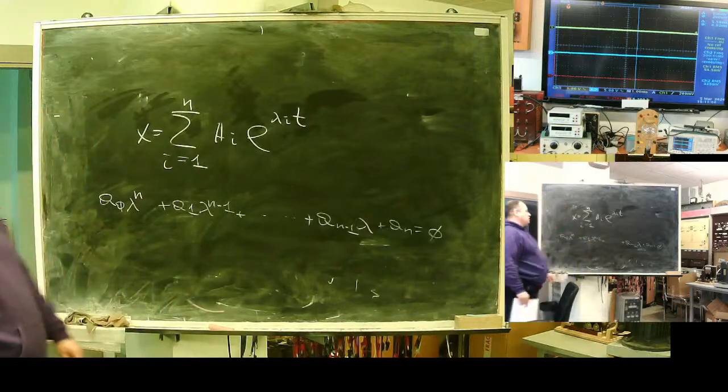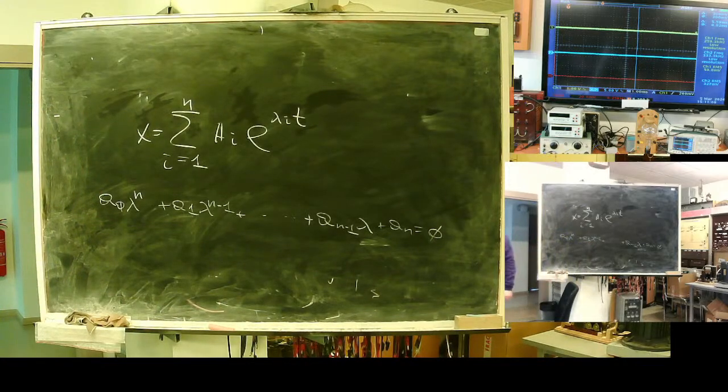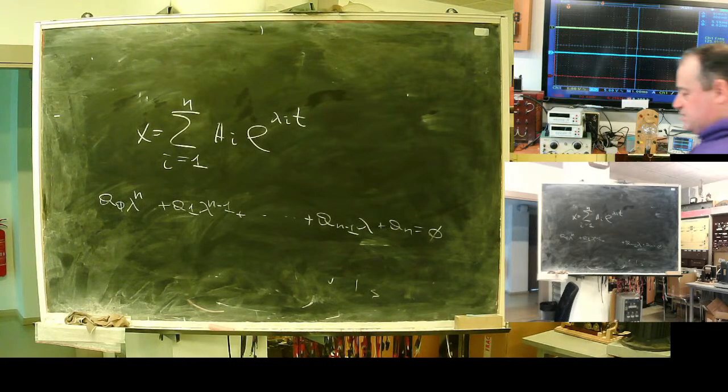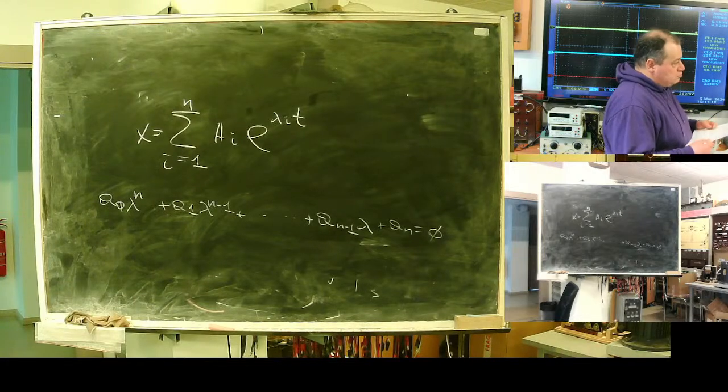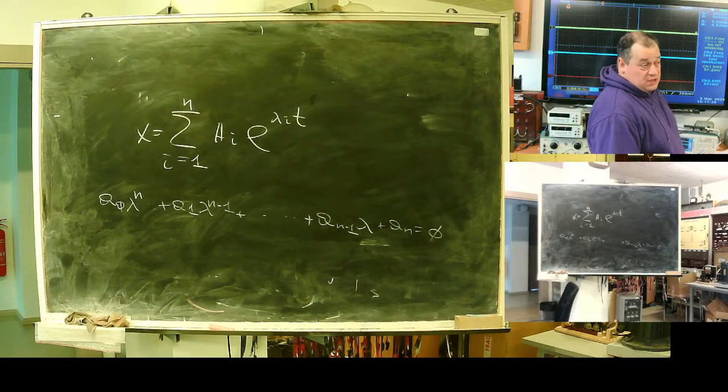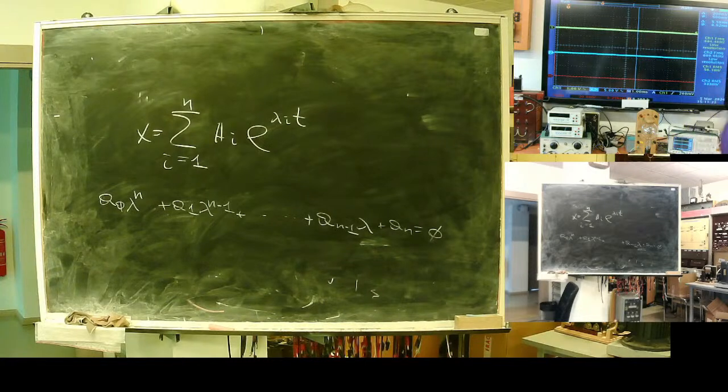Solve this equation and you will get the roots of the characteristic equation. For a system that can oscillate, these roots give own frequencies or oscillation frequency. For a non-periodic system you will see only decays.